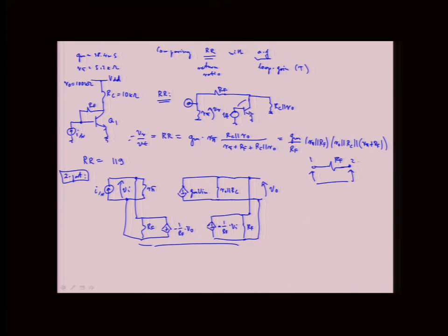Yeah. So as we did it last time, in practice what you would do is this circuit, right? You would just say, okay, I have I in, and then here I have R pi, and then here I have RF, and then what happened with this node, I grounded it because it was shunt, right?